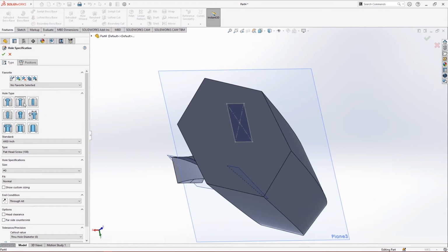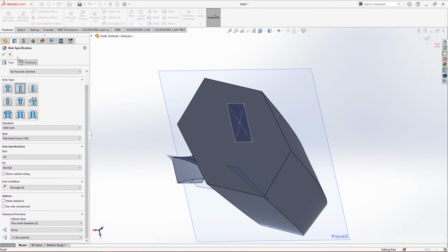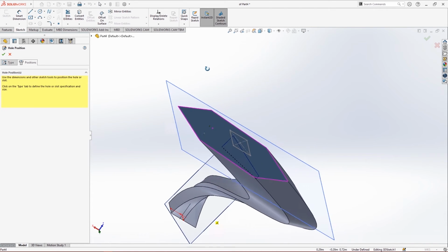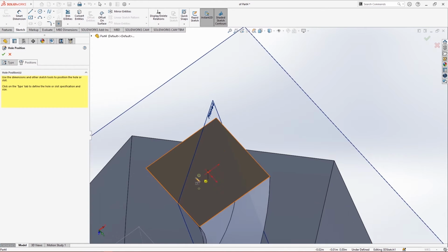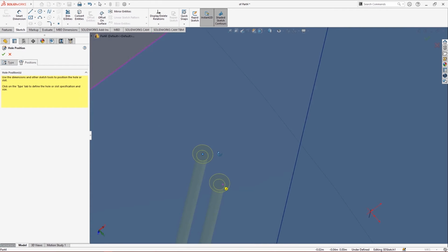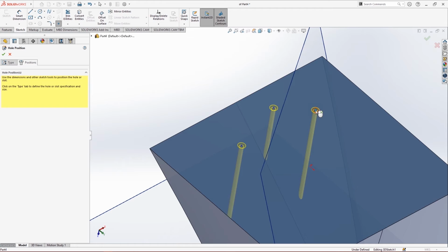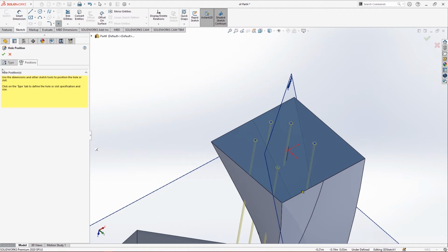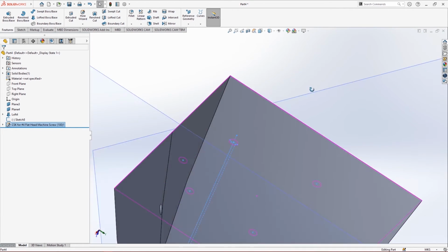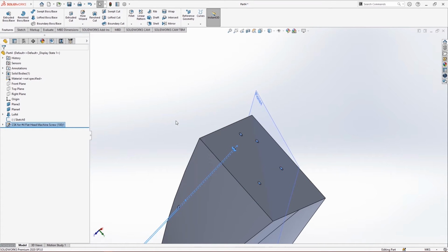I have selected the tapered hole in size inch. You choose everything, size you can select. I want M4. Okay, now for the position, you click on position, and it will ask you to draw a 3D sketch. I want the hole to be at the top of the surface. I go here and you can see the yellow thing. I just dropped it. You can make multiple holes. You just click anywhere, it will drop holes right there. And just click OK. You can see I have holes here, at 5 places. So this makes the whole process pretty easy, you can do anything at any place. Okay, the hole is done.